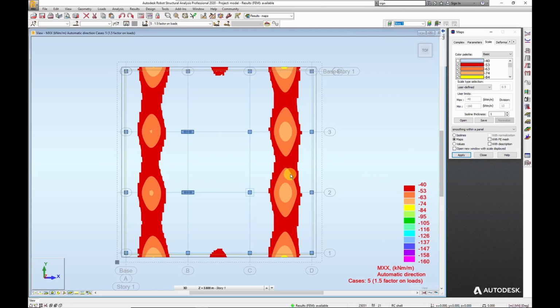But what this is telling me is that if I've got a base mat of reinforcement, and just as an aside, in terms of a way of approaching design, I think it's often a good way to approach the design of reinforced concrete slabs to think of the buildability, to think of what a standard mat of reinforcement might be for your particular case, what the spacing of the bars might be.